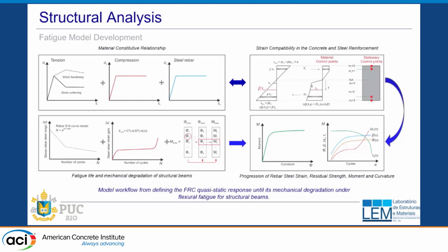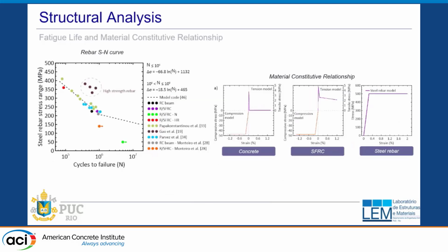Calculate from that stress, calculate the effective strain due to the fatigue, and this strain is added to the initial strain, which would be the load that's applied. This function gives us a moment curvature, and with the moment curvature response, which is basically a summation of these, we can actually calculate what's the residual capacity of the overall structure.